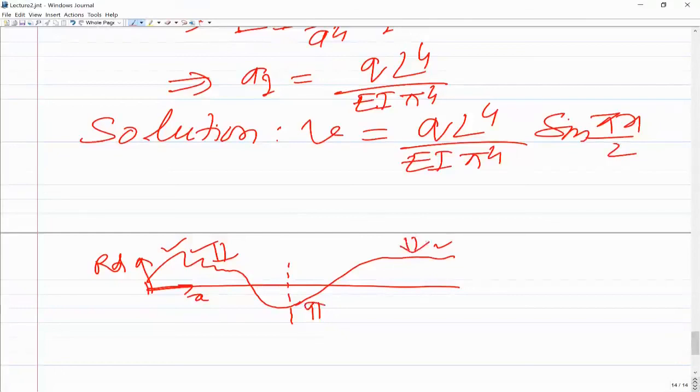That is what the weighted residual statement actually means: we have some residual, we put some weight, and by putting that weight we try to bring it closer to 0. In collocation, of course, at one particular point you are exactly making it 0, but in the process at other points it might increase. If you have more collocation points, it will be 0 at all those points, but other places it may be more. When you keep increasing the collocation points, you will find that at most places the residual would be closer to 0, and that means we would be closer to the exact solution if we have more collocation points, which means more terms in the approximate solution.